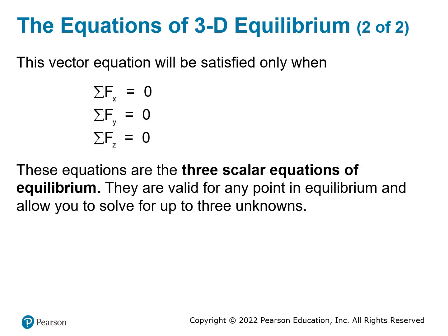You make each one of the net forces equal to 0, and this is what we call the equilibrium equations. Again, when you write those equations, make sure that you define your positive direction. For example, let's just draw an example of the axes.